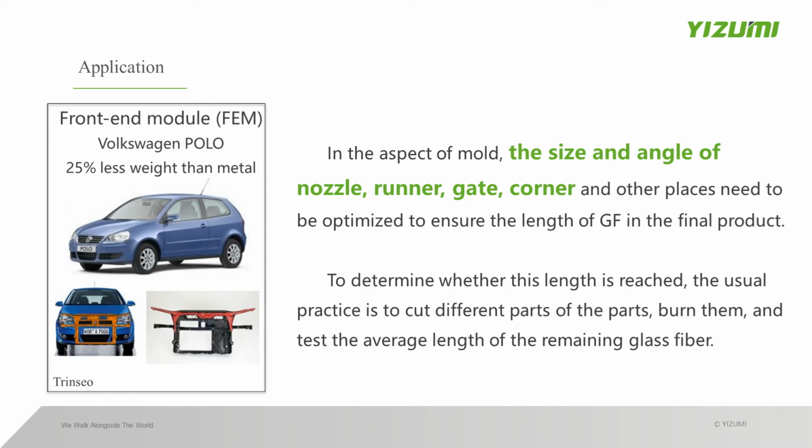In terms of models, I highlight here the size, the angles of the nozzle, the runner, the gate, corner, and other places that need to be optimized to ensure the length of glass fiber in the final product. Because glass fiber can be cut by the flow and high shearing, and maybe after this they can meet the design requirements of the final products.